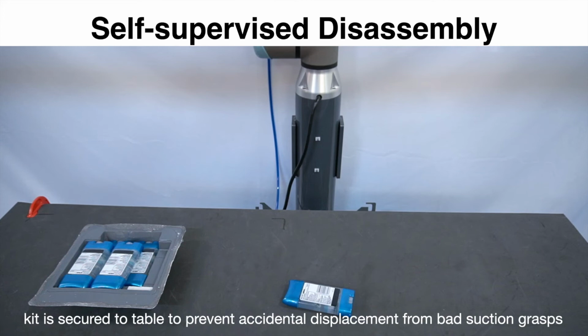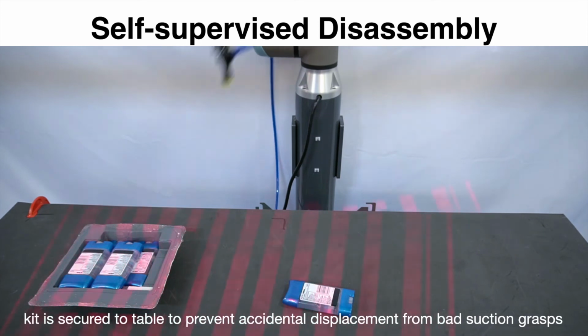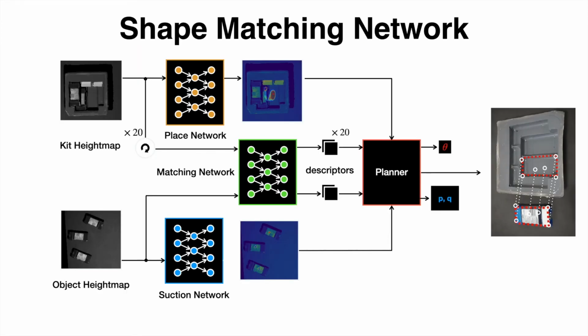To make the disassembly process easier, we fix the kit to the table to prevent accidental displacement from bad picking attempts. The core component of Form2Fit is a two-stream matching network that learns to infer geometrical correspondence for the object and their target placement location from visual data. Since these descriptors are orientation sensitive, they allow Form2Fit to infer how to pick and rotate the object before placing it in the target location.